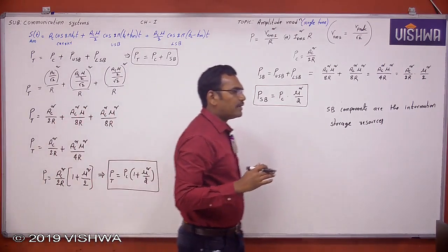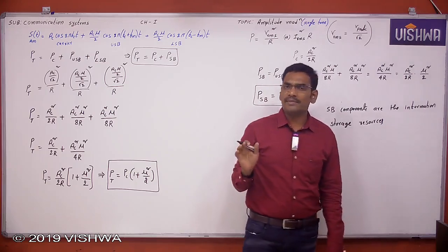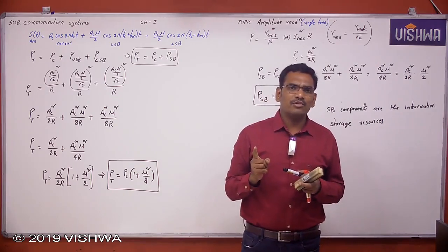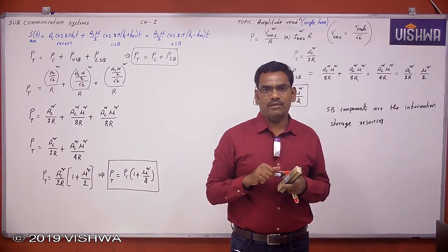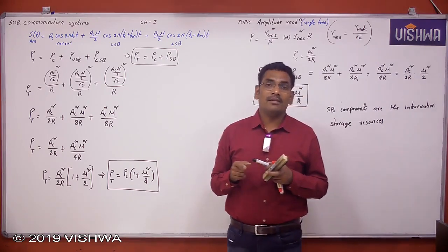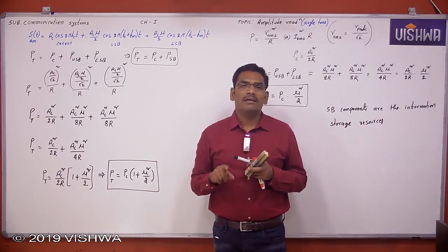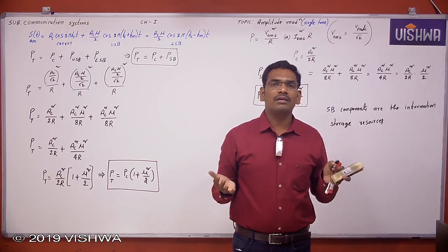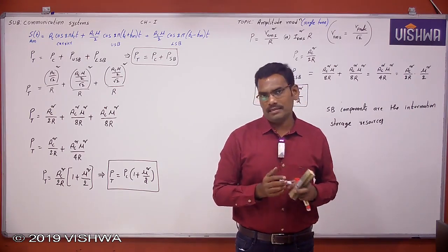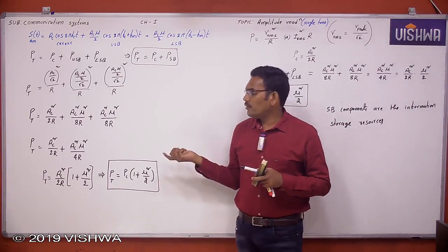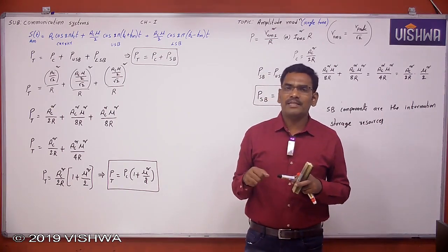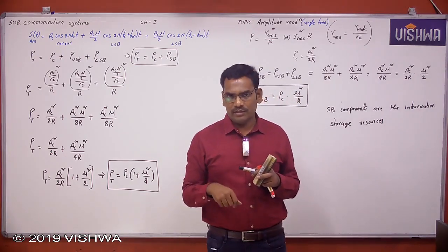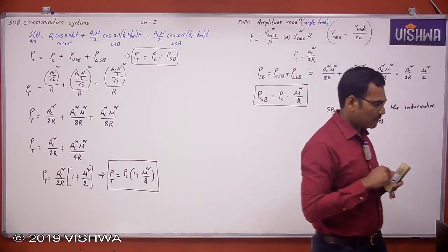Now, this is the power calculation, the power required to transmit the AM signal. The bandwidth of the modulated signal, or any signal, should be as low as possible. We can accommodate more signals, meaning multiplexing is good, when the modulated signal bandwidth is less. Also, the power required to transmit the signal should be as minimum as possible, because less power is an advantage. Okay, this is the power calculations. Note down first.